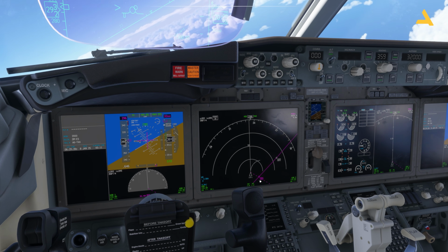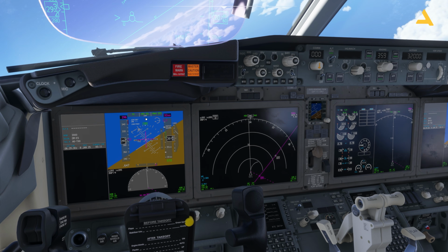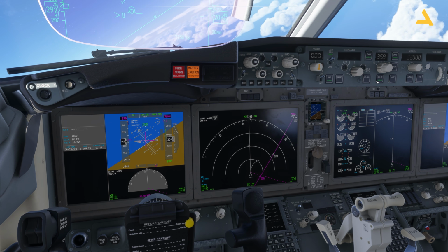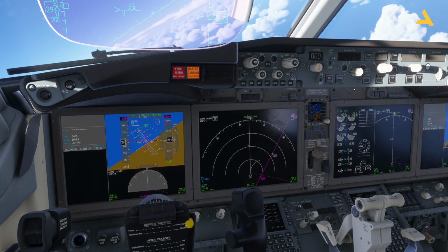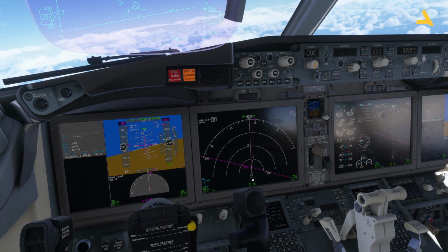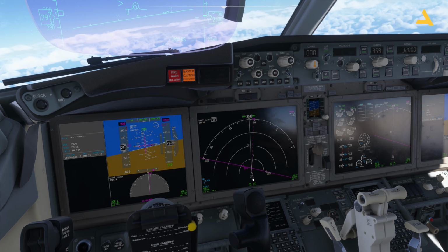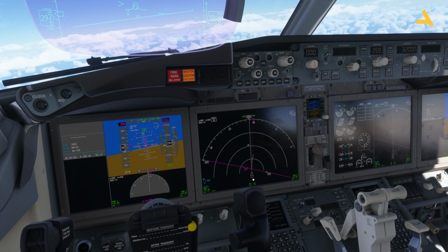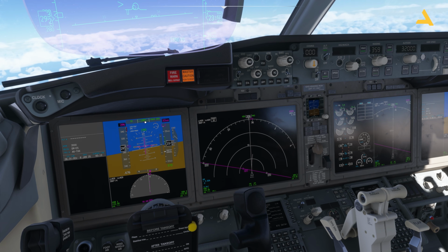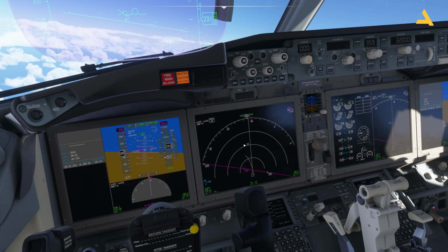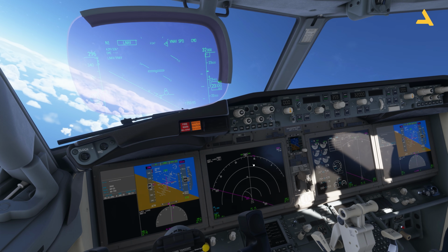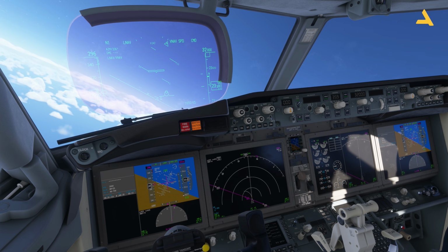As soon as the plane is near this flight plan, it will again go to this LNAV mode because LNAV is now armed. And heading select mode is the current mode of navigation. Let's see when the plane will follow this flight plan. Now the deflection is 1.4 nautical miles towards left. Soon the nav mode should become active, and yes, now it's active. So this is how you follow the flight plan if you face any deviation during the flight from the flight plan.